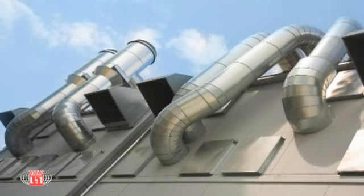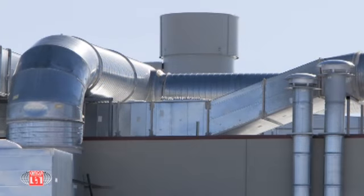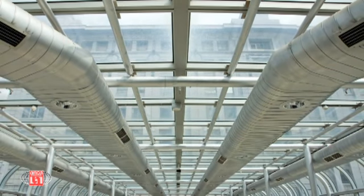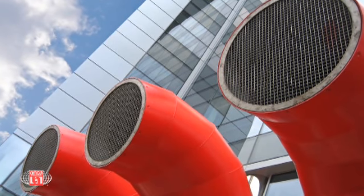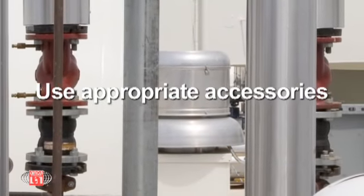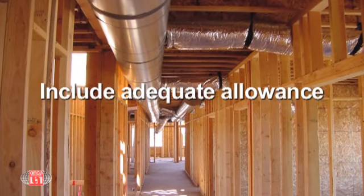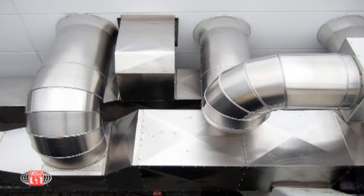So, remember these simple recommendations to minimize system effects. 1. Allow enough room as necessary in the building design to avoid system effect when connecting fans to the duct system. 2. When space or other factors dictate a less than optimum arrangement of the fan outlet and inlet connections, use only accessories and appurtenances that do not create significant system effect. 3. Include adequate allowance for the effect of all accessories and appurtenances on system and fan performance.